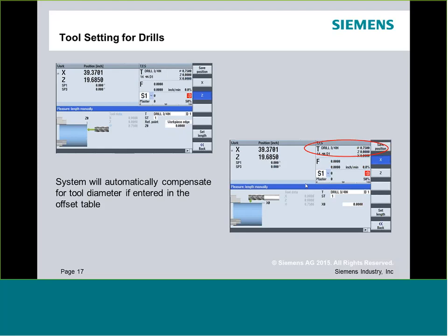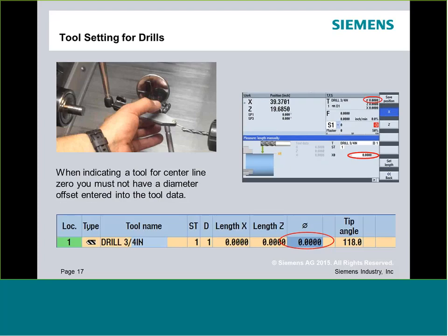So the problem is, when I'm setting up a tool, I don't normally touch off to the side. If I'm setting up a lathe, I'm typically going to sweep the physical holder. So if you look in this next image, here would be a nice little example of how I would generally set up a drill. I would place the drill dead center of the center line of the spindle. My mag base is on the spindle, and I'm rotating my indicator or my coax or whatever I'm using, and I find the middle of the tool.